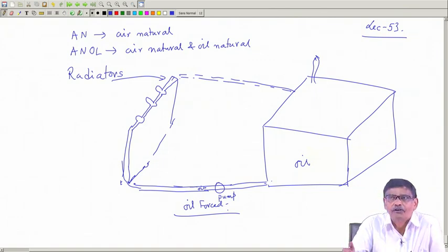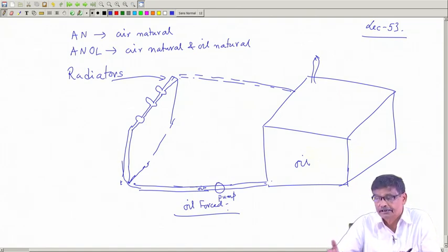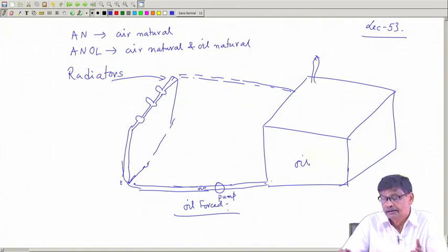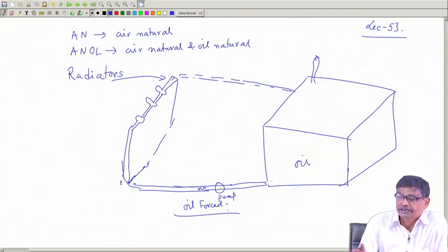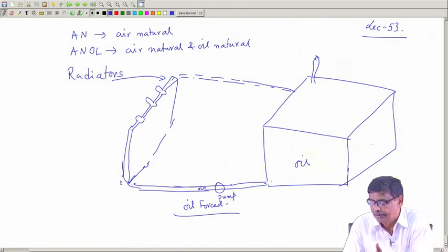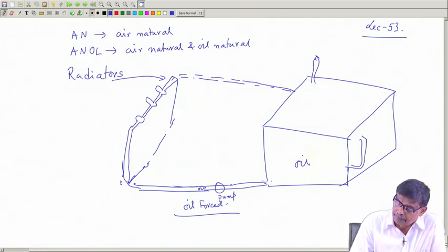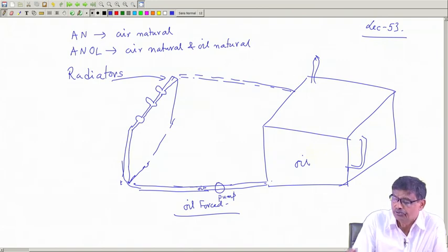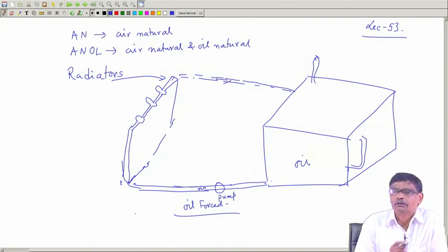Therefore, since you have gone for higher kVA rating, the size of the transformer has increased, and you must have elaborate arrangement to artificially increase the surface area of cooling, and heat will be radiated not only from the usual tanks here, maybe tubes also connected, natural circulation of the oil here, but also force the oil to move through the radiators to make a closed path, and oil will be circulating.